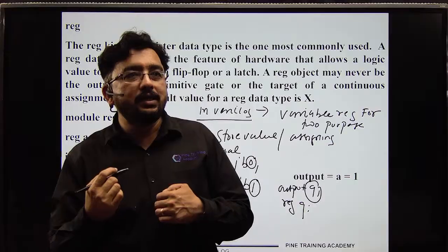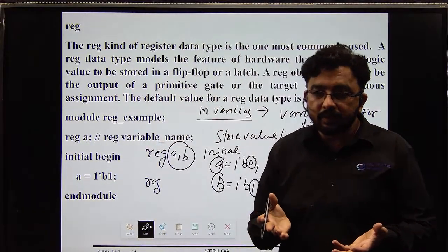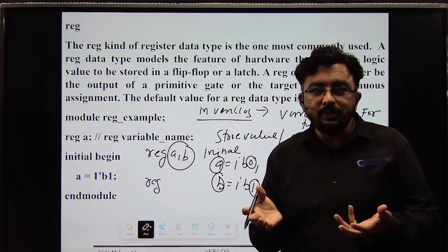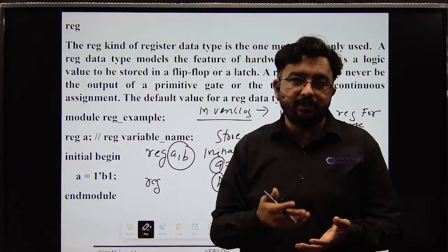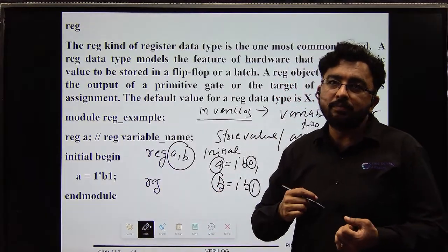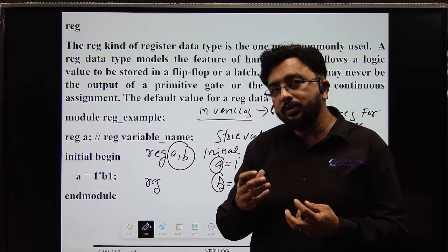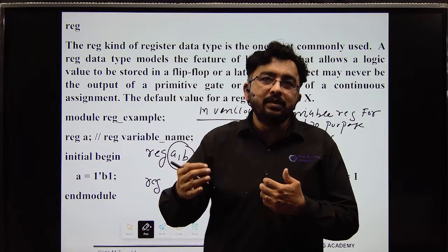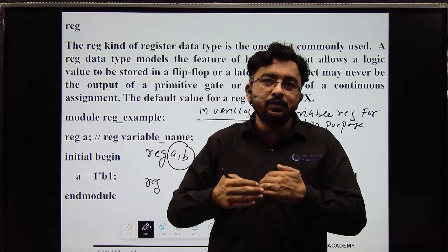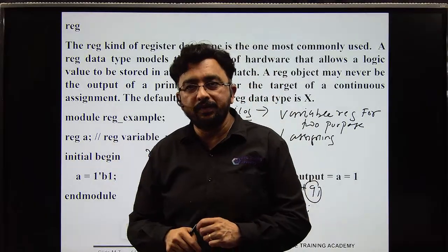Because in continuous assignment the data is not stored. Okay, data keeps changing. But in a procedural assignment statement, the data is used to store the value, and to design something where you are using that particular value to take the output of some other value.